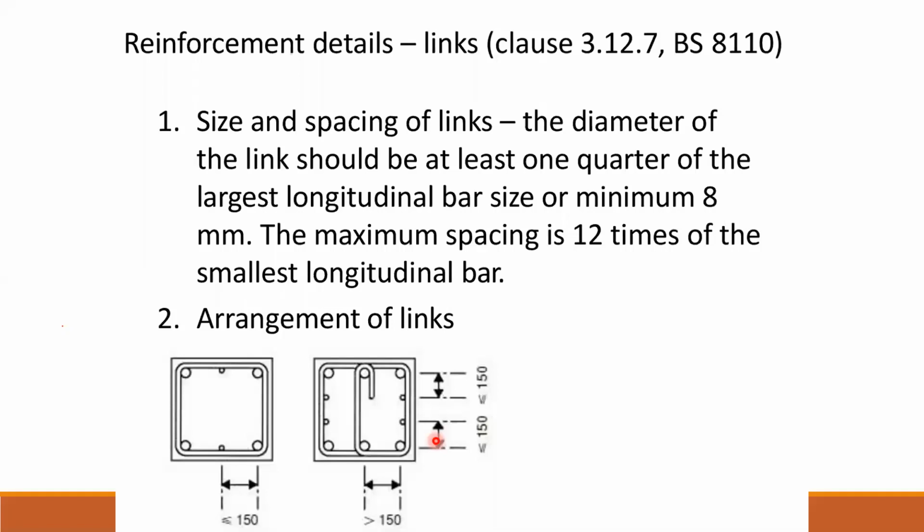millimeter. In Sri Lanka there is a common issue, we don't have much 8 millimeter diameter steel, right? So people are using the 6 millimeter bar for the hoops and the links. As it is important to follow the code of practice, it is better if you could find the 8 millimeter bar.